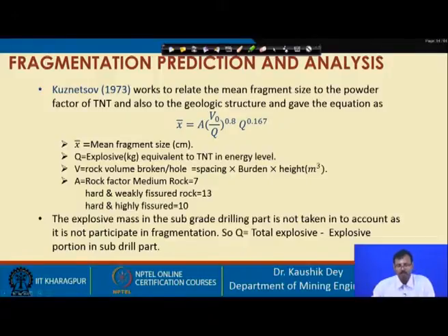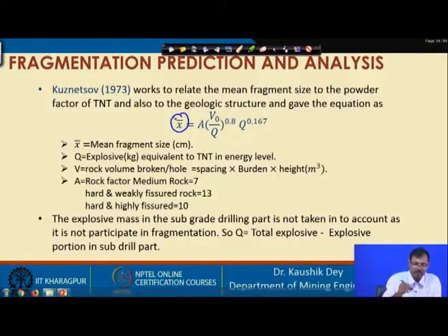So, this is the first model given by Kuznetsov to get the mean fragment size, and this depends on the rock factor, the volume of rock broken, and the explosive charge quantity equivalent to TNT.